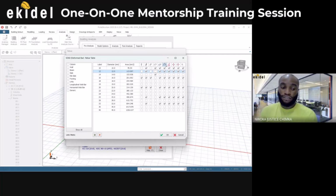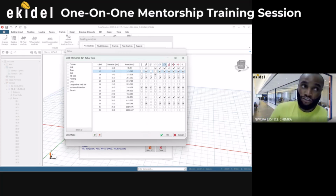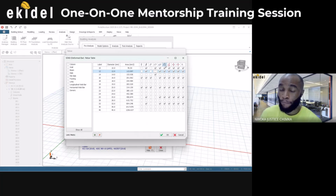Now since we are using a pad foundation, I can choose to leave it, because this is for a pad footing. So I'll skip this one. Then go to links. In my country, we used to use link diameters of 8 or 10. I don't know what you use in your country.